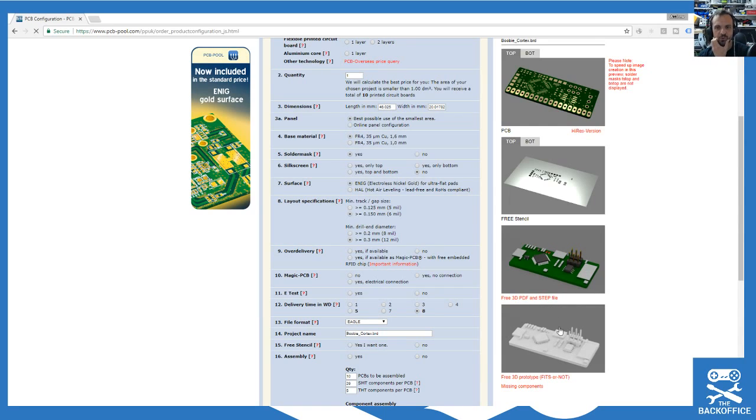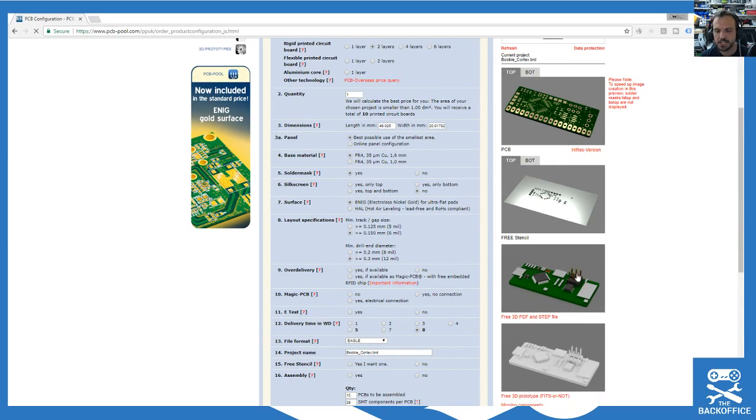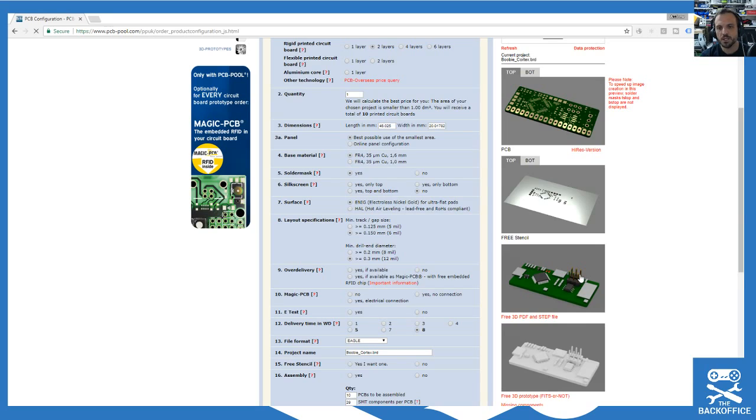So that's what the board will look like if one puts long pin headers on it rather than just little solder jumpers. So the reason for these pin headers here, one is to enable the termination resistor on the end of the CAN bus, and the other is to enable the programming mode. I'll leave them on. I'm not going to redesign the board just to get rid of the pin header, because we'll work out whether or not we need it.